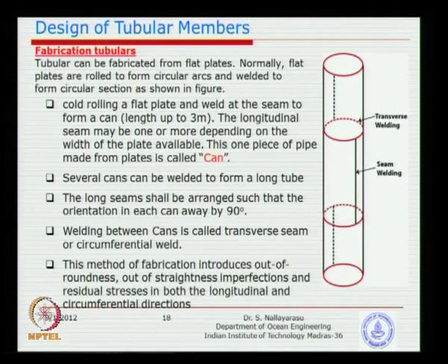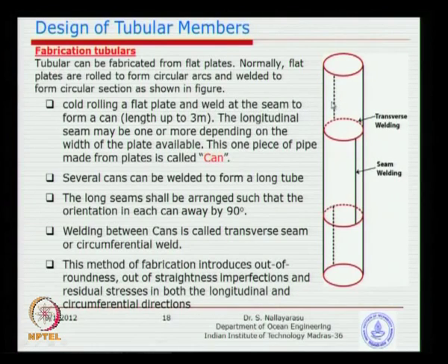Now every time you do welding, stresses develop due to heating of this material, because you are not heating the material to the same temperature throughout; only along the weld locations does the temperature increase, elsewhere it does not, so the material will try to expand. Wherever expansion is possible, stresses may not develop, but otherwise there will be a build-up of stresses because expansion could not happen.